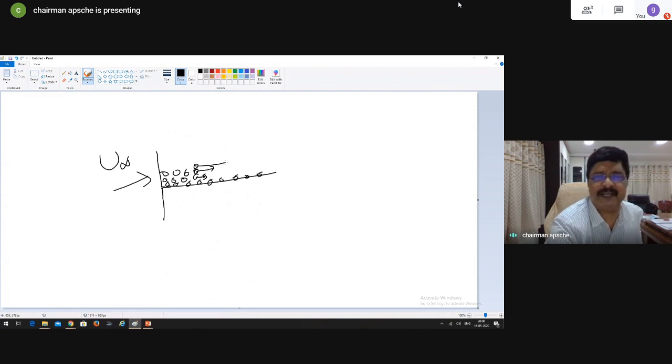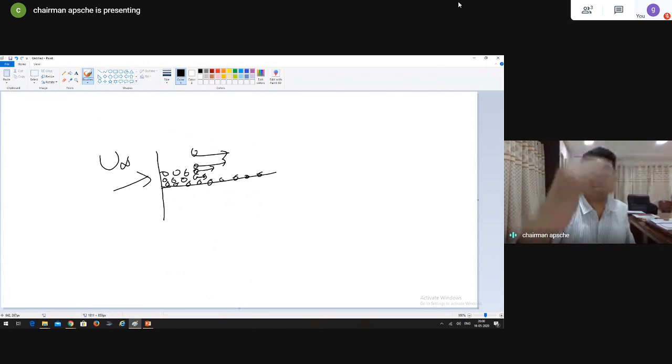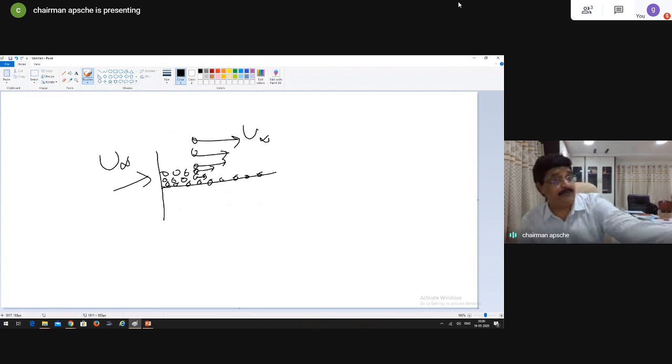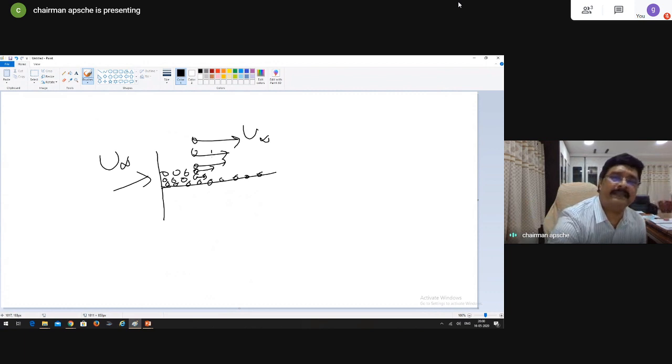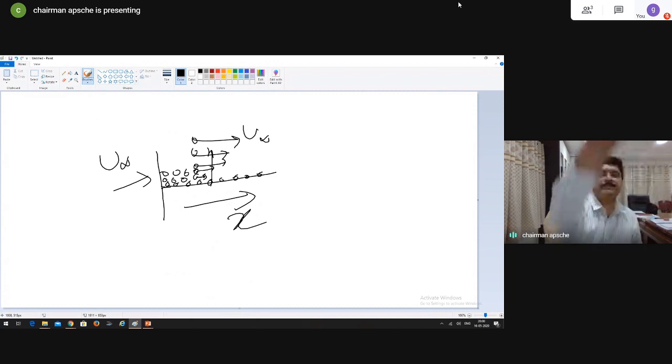Similarly, the same explanation can be given layer after layer. As you move away from the plate, the wall friction effects and the inertial effects are not felt, and finally there comes a point where the molecule will be moving at the free stream velocity, because before reaching the plate the molecules were moving at the free stream velocity, right? The same free stream velocity is regained by the molecule after a certain y distance. Let me say x is the direction of the fluid motion and y is perpendicular to the plate.